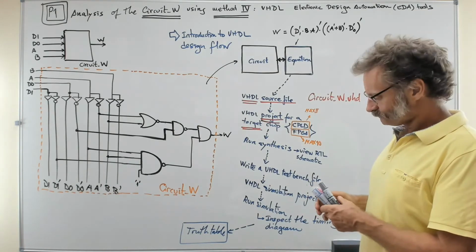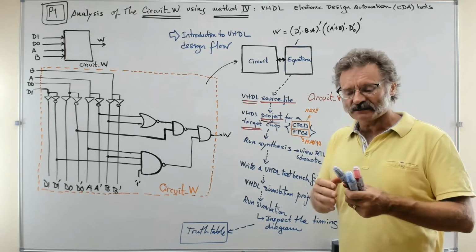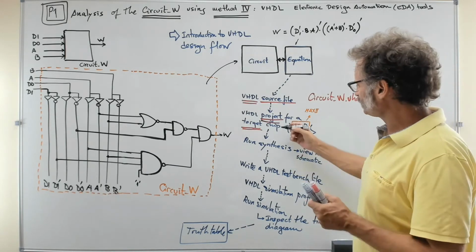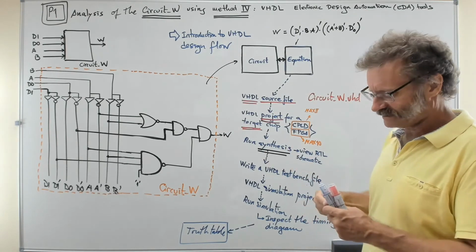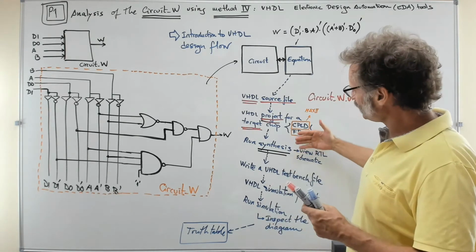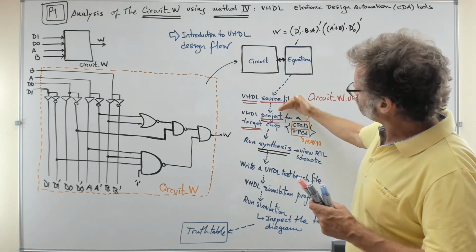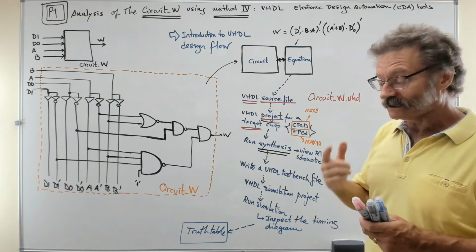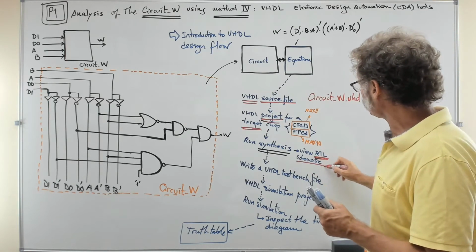So once the project is organized around the project navigator, we have a job to do, and basically the job is called synthesis. That's the first task. Synthesizing a circuit means in some way going back from the equation expressed in VHDL to the circuit. So we will inspect this circuit, and it is going to be called the RTL schematic.